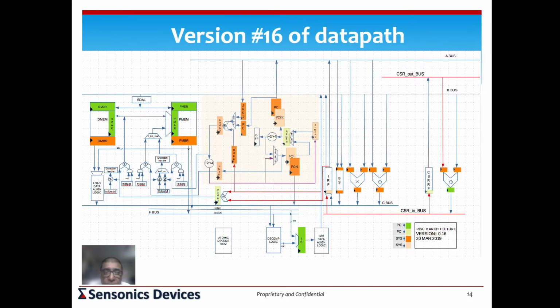There's a whole bunch of config registers under CSRs in the privilege mode, where you can set, at very close resolution, I think 4 kilobyte resolution, memories where each chunk of memory can be programmed to be readable, writable, read-write, or executable, and all kinds of combinations for each one of those. So if a particular zone in program memory is writable, you could actually write to that memory.